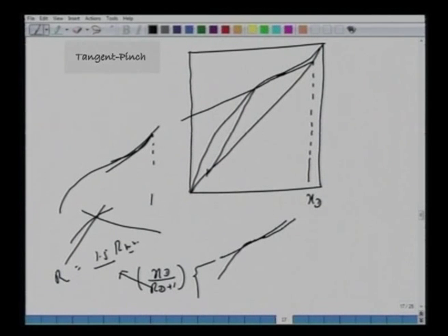All right. So in today's lecture, we would like to summarize that, essentially, starting from the Q line and one of the operating lines, we can draw the second operating line, or we can take the two operating lines and draw the Q line. So we have three line equations. One is the Q line, which we obtained from the energy balance, and we have the two operating lines, which we obtained from the species balance. Knowing two, the third can be found. And then we can do this construction of the trays.